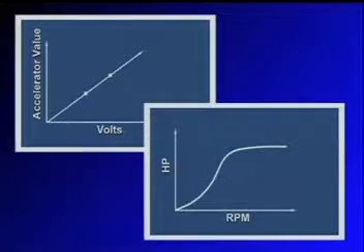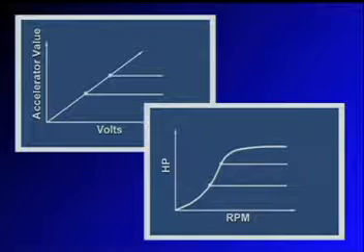The industrial accelerator default feature determines the default accelerator values to be used when certain accelerator system errors become active. Depending on the fault condition, the accelerator value defaults to one of two calibratable values. The intent of this feature is to allow continued engine operation at sufficient power to maintain accessory loading. When this feature is enabled, it replaces the accelerator limp home feature.